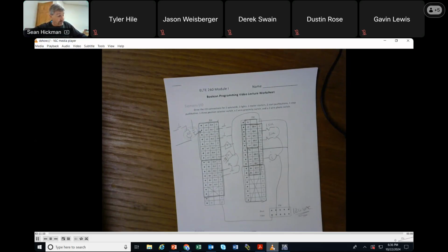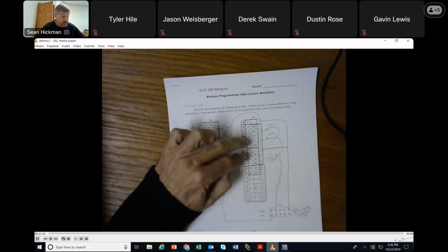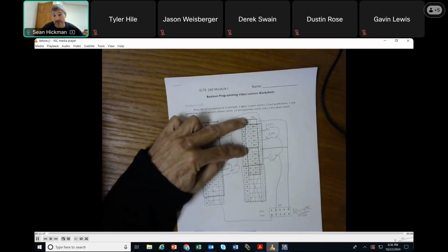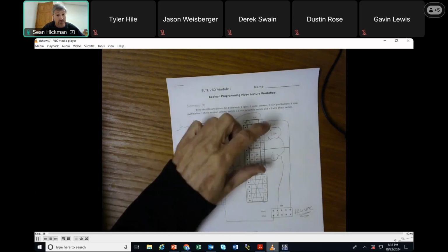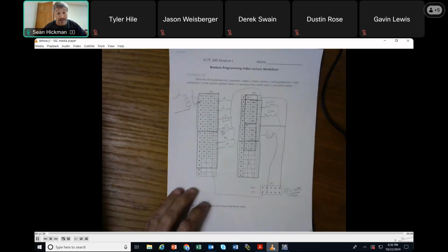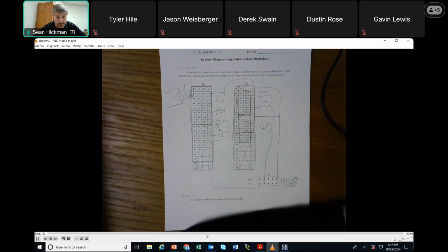Now the outputs here, they're relay. So my 1L and 2L, I could wire it, whatever. I could wire 12 volts DC, 24 volts DC, 120 VAC, 240 VAC. I can wire whatever I want in there, and they're just a contact that's closing. So that works fine here with our devices. So that is the I/O of the trainer.